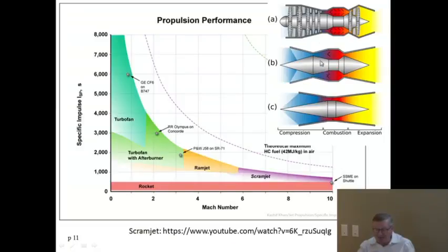Here you have a high pressure front, and that's where you inject the fuel, and then you go through a nozzle, which transforms the enthalpy back into kinetic energy. This can all be done at very high Mach numbers with a different shape of these things, and that's then supersonic flow. That is another elective, later or graduate level class.